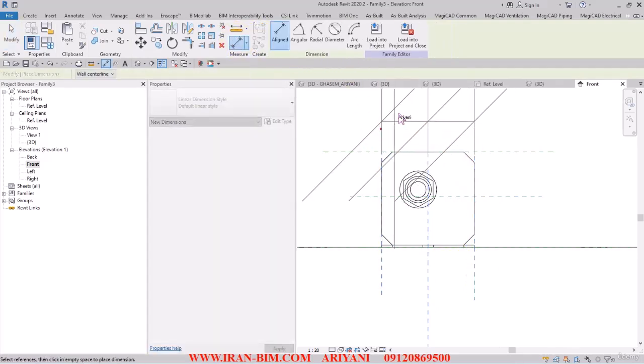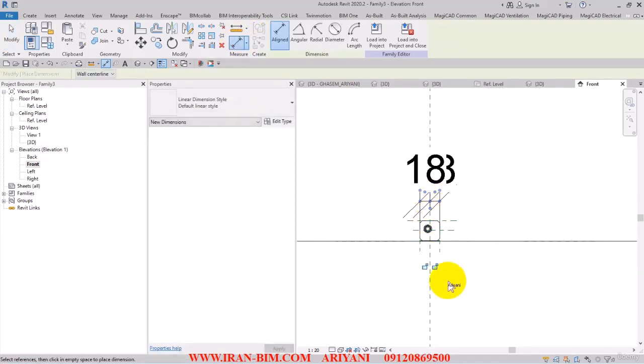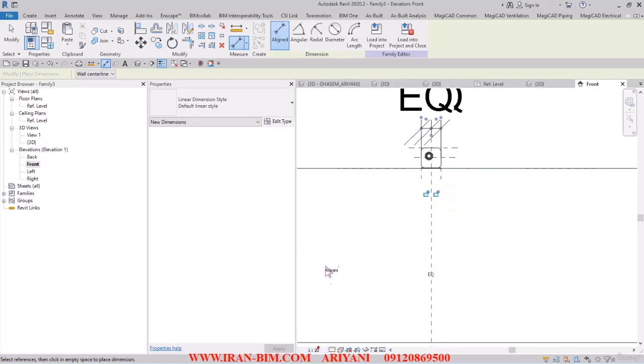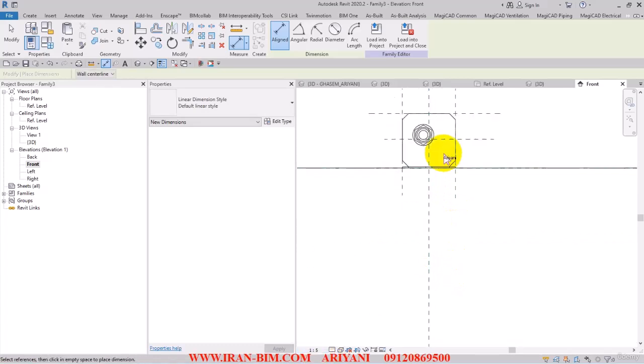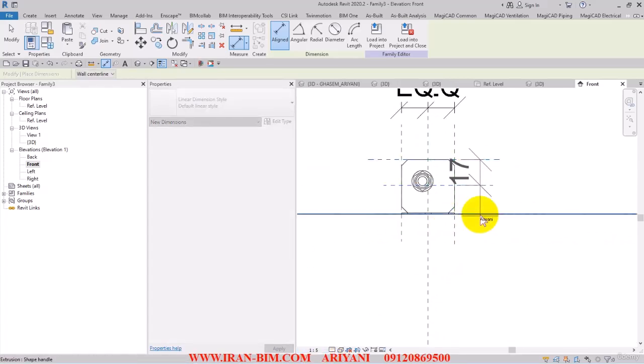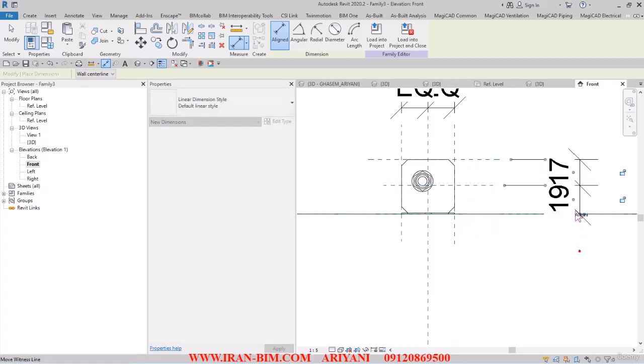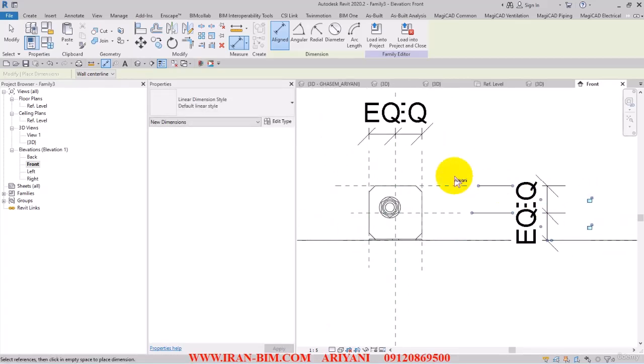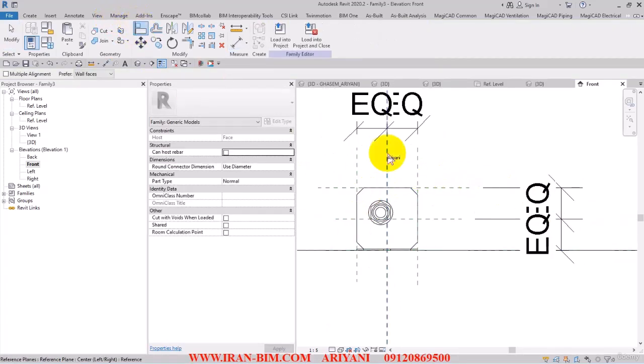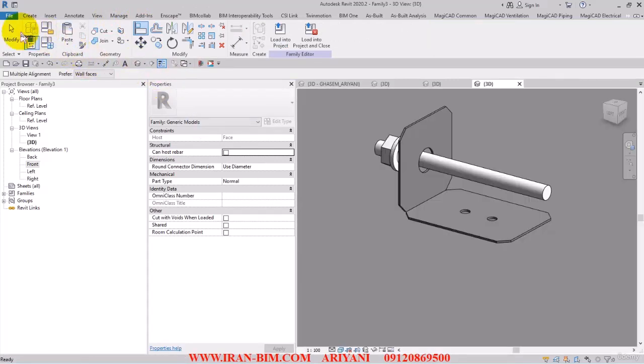After that, draw a couple up here, and then let's put the scale to 1/5. Then we go back to the shape and put this here and equalize it. Then using align, we'll lock the bolts with this one and then this reference plane. And there it is with the bolts.